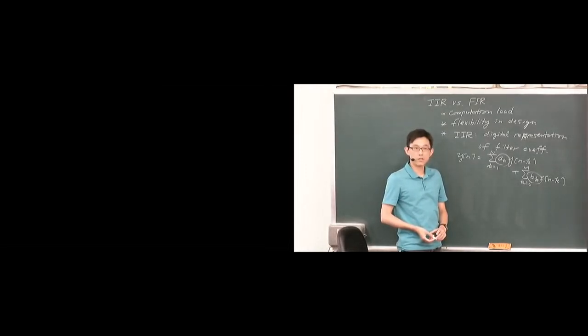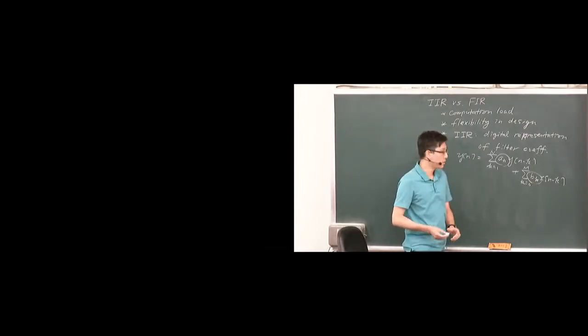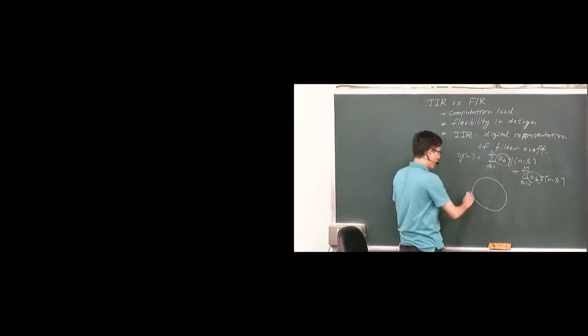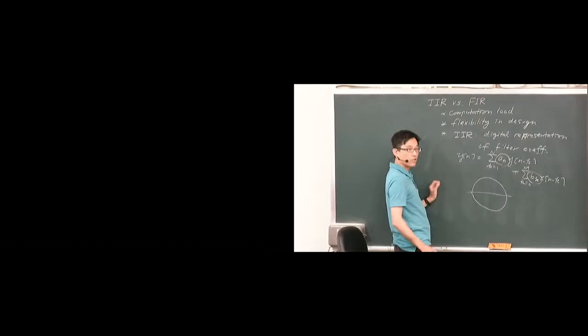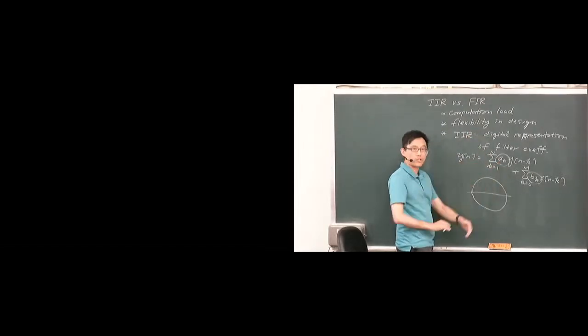We have said that FIR filters are always stable, and that's basically correct. And we also talked about when we design IIR, we need to be careful. We want to put all the poles inside the unit circle. So next week, after the midterm when we come back, we'll talk about a funny situation. Let's say originally you go through an IIR design, a Butterworth filter, right?